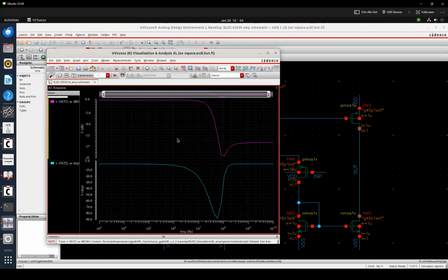You can see that the phase of amplifier structure or the buffer should look like 0 degree to negative 180 degree, right? But it goes back to 0 degree. And its amplitude also goes back to some value. So this means that there is some zeros. So we have pole at 3 dB bandwidth, but there is some zeros.